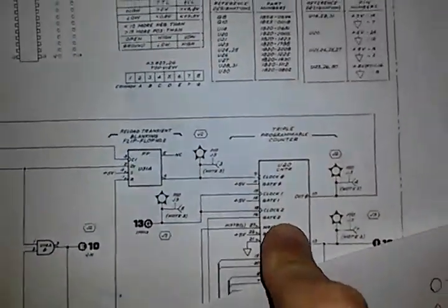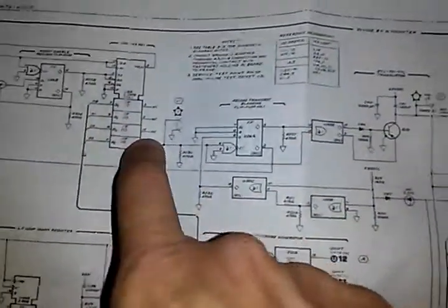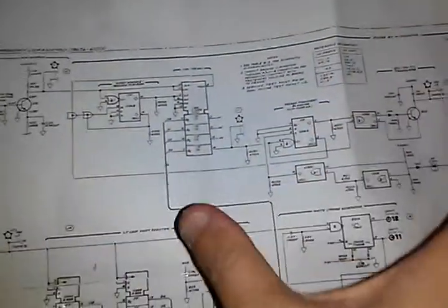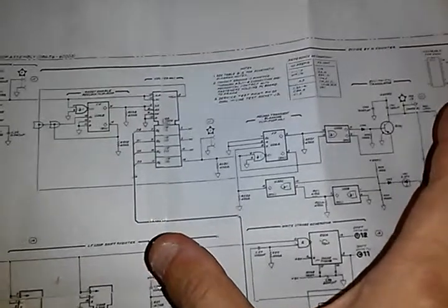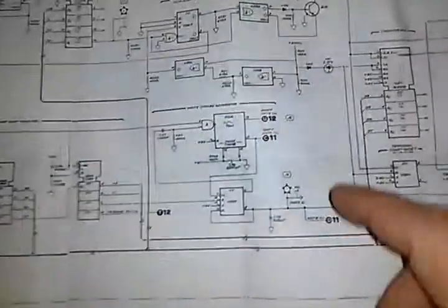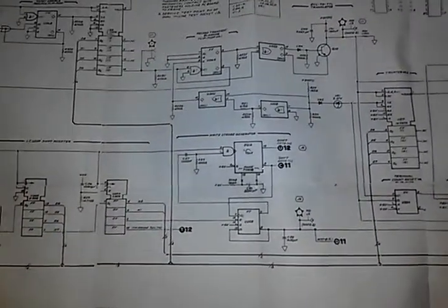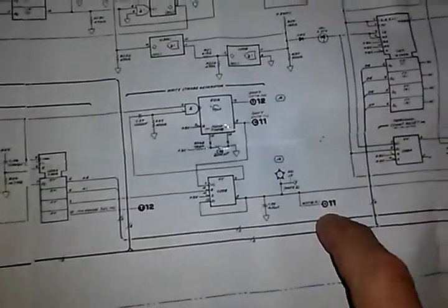Yes, U20. Now, whenever the frequency is changed within the band of 25.6 kilohertz, only this gets written and this gets written. This is not changed. Anytime it's within a band of 25.6 kilohertz, this never changes. And that fact is used to strobe the high slew rate pin on the phase lock loop phase detector, which is located on schematic number 11.